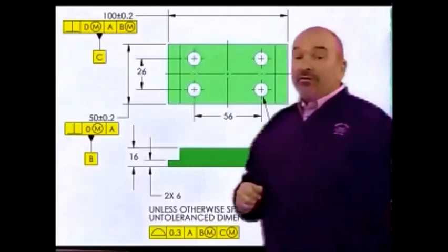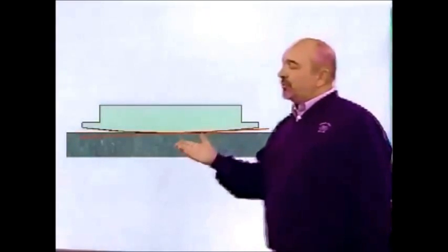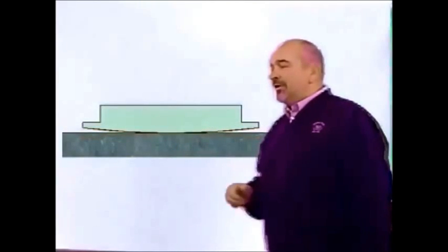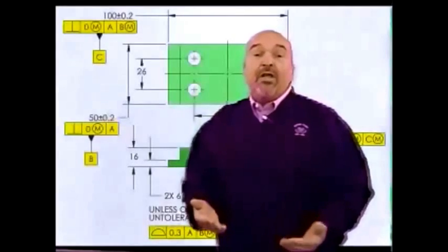If the surface is convex and I place it down on the surface plate to inspect the part, it might rock around a bit. This is showing you that there are several different datum planes that I could possibly use. In fact, if I set it down and it does rock, there's an infinite number of planes. So which one do I use? Well, if we look at the Y14.5 standard, it says you pick the optimum one.